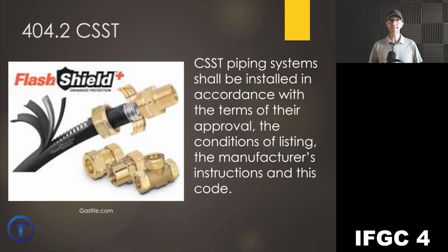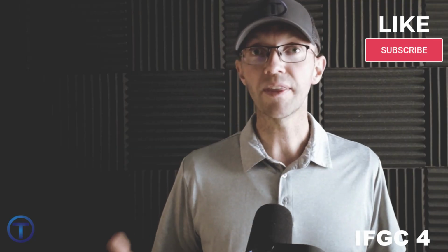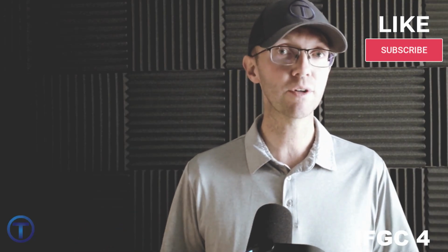404.2 talks about CSST. CSST is corrugated stainless steel tubing, and it says these piping systems shall be installed in accordance with the terms of their approval, the conditions of the listing, and the manufacturer's instructions, and this code. We're putting all these angles on it, but we have to make sure it's installed correctly. Now, just because you know how to install one type of CSST from a certain manufacturer doesn't mean you know how to install them all. They do have different fittings, different connections, different methods for installation. So if you're installing CSST, you need to make sure that you understand that system. Ideally, you've been trained and certified on the installation of that system, and then you can go forward with confidence that you're going to do it right.